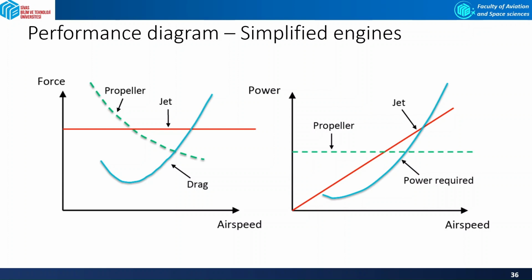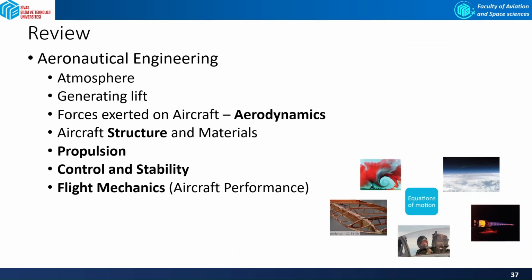Because of this different behavior of jets and propellers, we normally use the force diagram for jet and the power diagram for propeller engines. You will see in the performance course that these diagrams combined with the equations of motion will allow you to do many aircraft performance calculations.